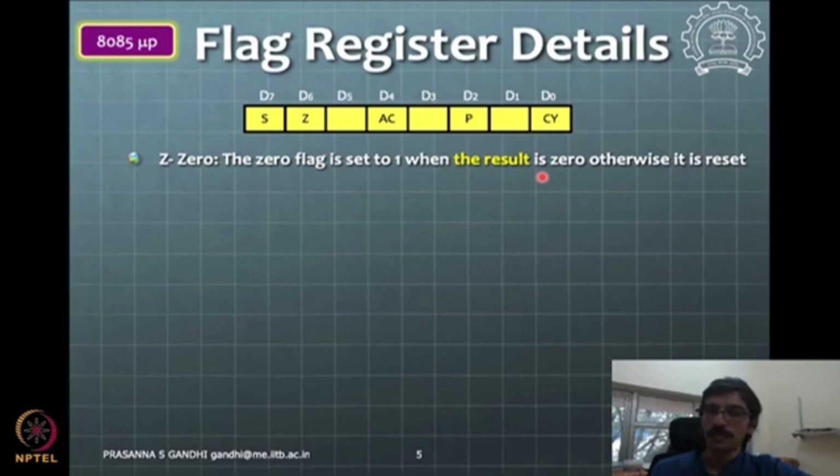Okay, so this flag register is used for many of these control commands that you typically see, like if and while loops. Those kinds of breaking or looping, or coming out of the loop, or conditional operation execution all depend upon this flag register. So the flag register plays a very important role in any microcontroller. You may not be able to see it as a part of the architecture. It may not show up in modern microcontroller diagrams, but it is there anyway.